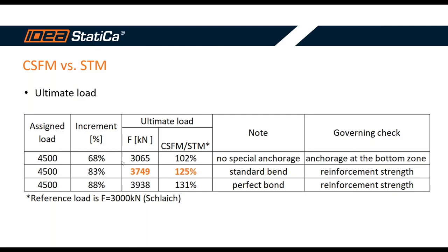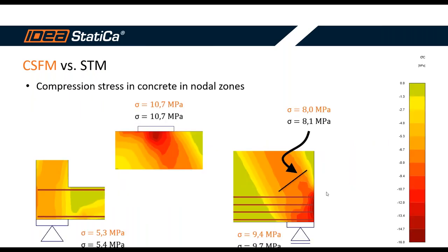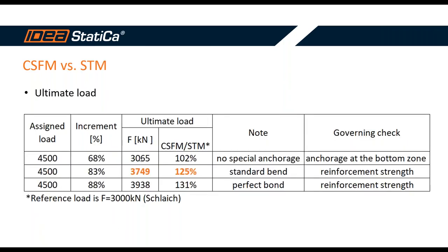The first model was modeled exactly the same as in the literature, but I didn't use any special anchorage at the bottom area, I mean here. So we got this ultimate load, which is equal to 3065 kilonewtons, which is almost the same as the reference load.